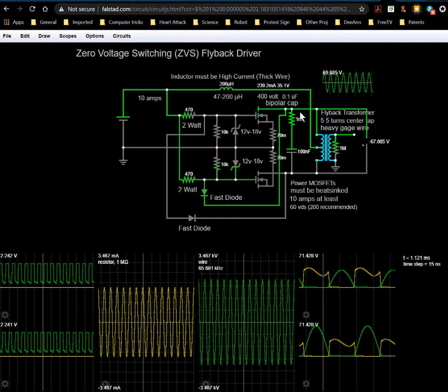So as a result, it's like 68 volts on top of the 1.5 volts we got here. So it's actually like 71 volts or so, technically, even though we're not quite getting that because it's not exactly at the same point. But the point is that this is a high voltage and this is ground, and since this is ground, current flows through here, which keeps this transistor off.